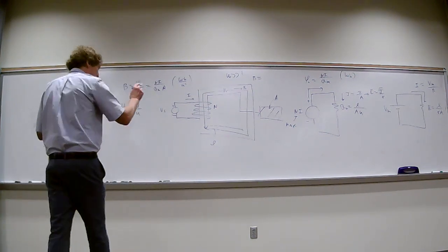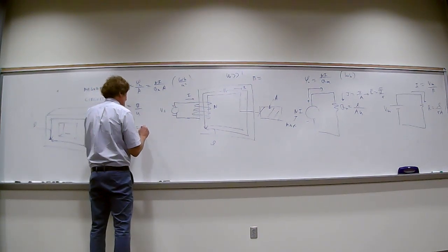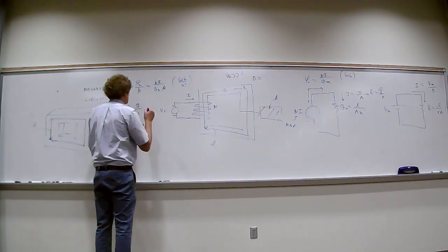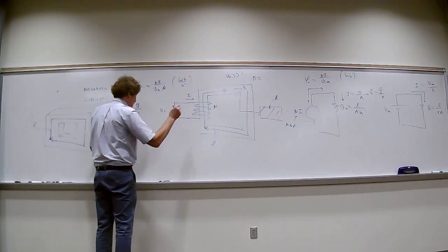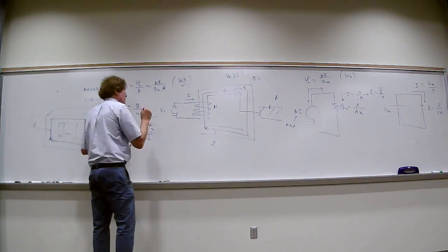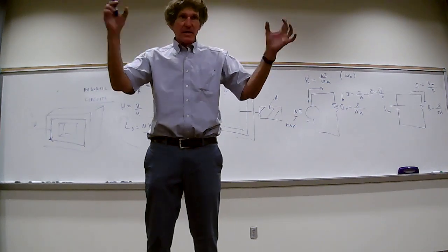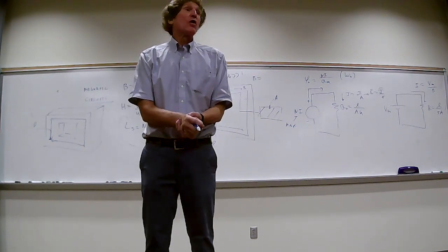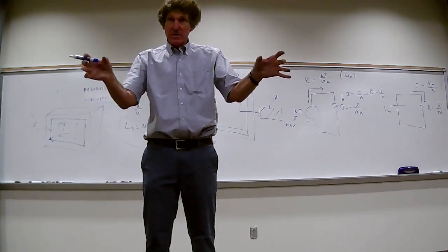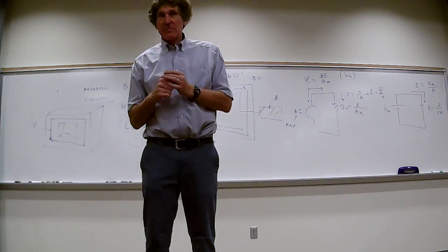So the inductance of that system would be equal to the number of turns N, because the flux flows through each one of those turns, times the magnetic flux, which is over there, and then you have to divide it by the current causing it. And this is a real easy way to get inductance for any system that concentrates flux that is caused by turns. It doesn't matter if it's a toroid, if it's a bar like that, or anything else. We'll talk more next time about this, and I'll give you a promise. Does everybody understand that?